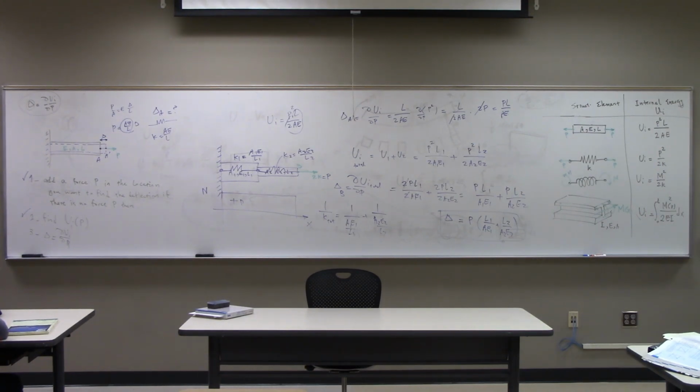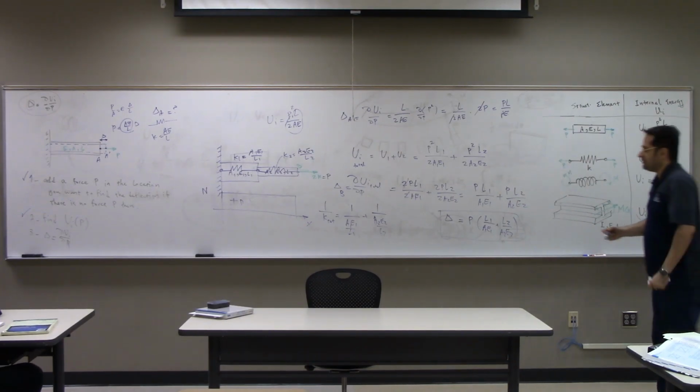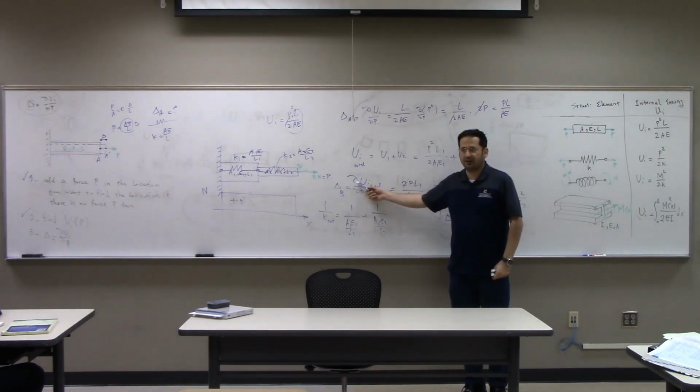So in this scenario you're talking about, if we do both methods, we'll get different answers. In a real life indeterminate structure, if you use, for example, the spring method, you actually do a lot of simplification. You don't do the internal energy of the indeterminate structure, right? And then you get the answer. When you use a computer, the computer does the internal energy.